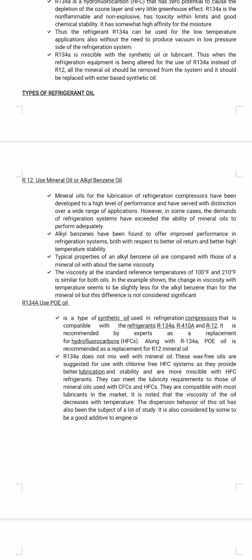However, in some cases, the demands of refrigeration system have exceeded the ability of mineral oils to perform adequately. Alkyl benzenes have been found to offer improved performance in refrigeration system, both with respect to better oil return and better high temperature stability. Typical properties of an alkyl benzene oil are compared with those of a mineral oil with about the same viscosity.